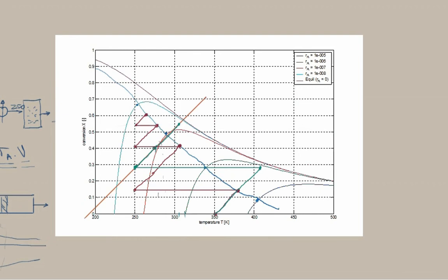So we are going to cool back from here to this point, and then we look for the next adiabat. Okay, I've drawn that on the wrong layer. Anyway, let's just draw it over there. So that's that reactor. Okay, and then let's shift our adiabat up here. Shift the adiabat here, and now you see we accomplish pretty much the same conversion as we had in that first case. However, we've done it now with 3 reactors.